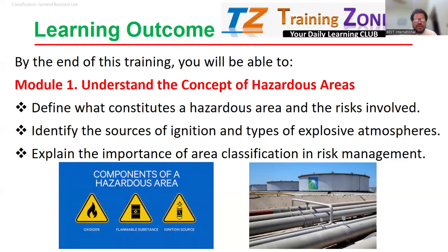But make sure without gas testing, we are not issuing the permit. Without isolation and lockout tagout if needed, we are not issuing the permit. Without a proper method statement, risk assessment, and some other studies, and verifying the competent individuals going to work in a hazardous area, we do not issue the permit, because the permit is kind of a legal agreement between the contractor and the client. If anything happens, both parties can definitely pursue it even in court. So it's a legal document.